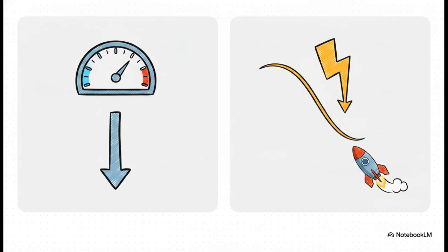If you drop the frequency by 10%, you save roughly 10% on power. It's a strictly linear trade-off. But because voltage is squared in that formula, the dynamic completely changes. If you drop the voltage by 10%, you don't save 10%, you actually get nearly a 20% drop in power consumption. That exponential return is exactly why minimizing voltage is basically the holy grail of CPU power management.